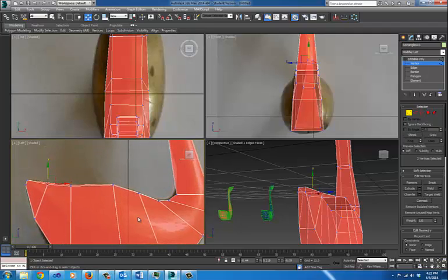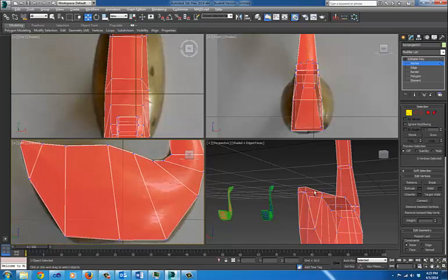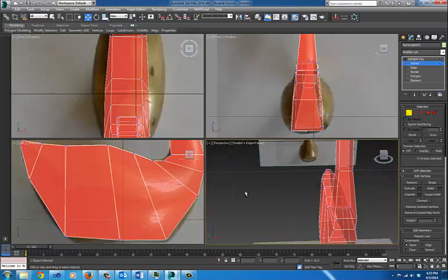What I'm going to actually do is now I'm going to go in for these vertices that are a little bit off alignment. I'm going to align them. So basically pick the two vertices up here, for example, which are the vertices on top of the swan there. And then I'm going to align them with the y-axis. And then I'm going to align these guys with the y-axis too. Reasonably set. Alright, so now this is the base body of my swan.